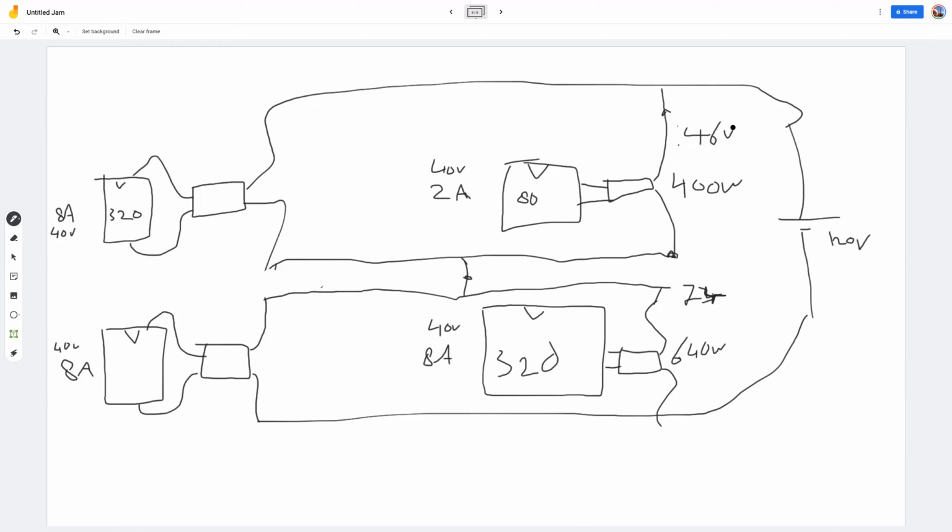Yeah, and we had two examples of doing it now. One of them was doing an intermediate tap on your battery. One of them was making a converter that transfers energy from the top side to the bottom side of the battery, and one of them is just to have more non-shaded groups in parallel with the shaded groups, so that the shade doesn't make that much of an impact anymore on the average voltages.